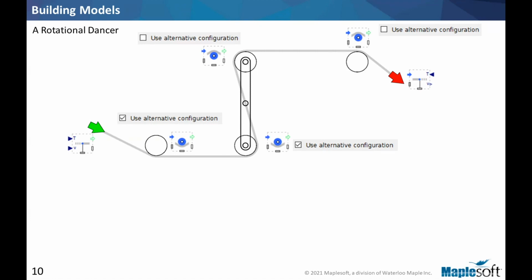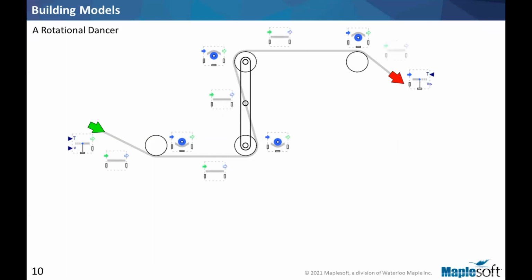You run the simulation, and if you made a mistake, you can rerun the simulation and select the right configuration. In this case, it's fairly obvious what we are looking at. So that's the rollers and the inputs and outputs. The next thing we need to do is obviously add the web spans to this. Web spans are the glue that connect everything together. So we have 1, 2, 3, 4, 5 spans between the input and output and the 4 rollers.